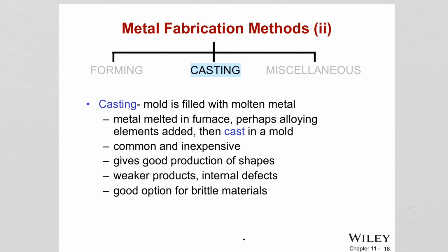The casting technique is employed when the finished shape is very large and complex and no other method may be practical. If a particular alloy has low ductility, then it cannot be formed easily by forming techniques, so you can do casting. Casting is also the most economical shaping technique.